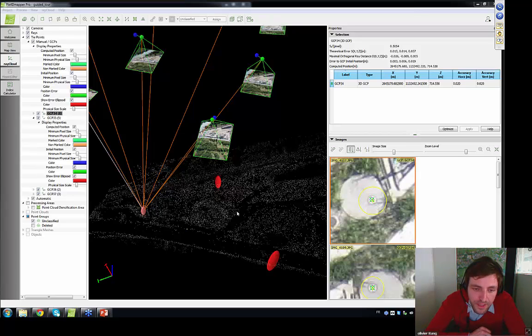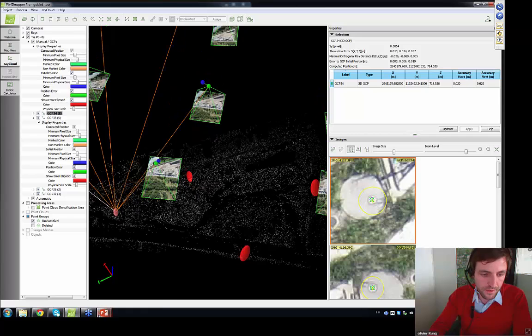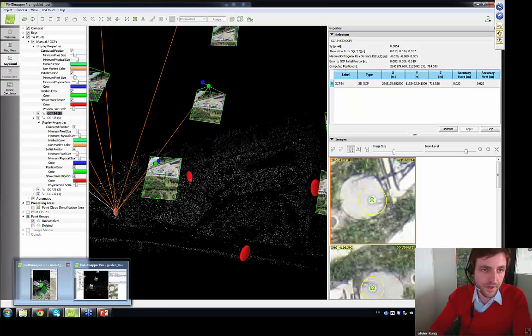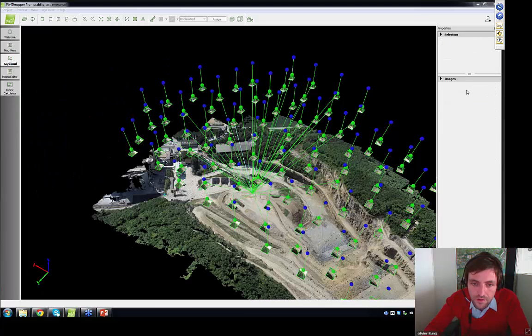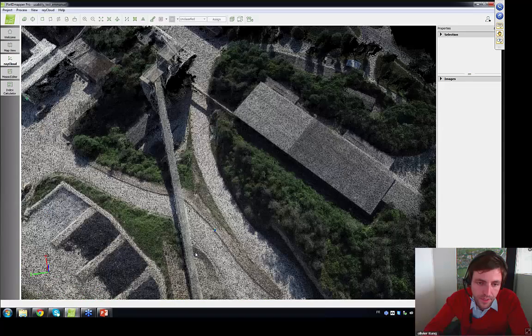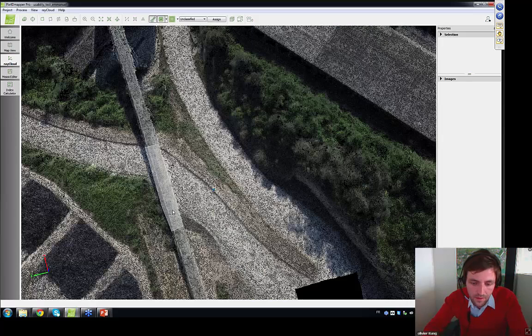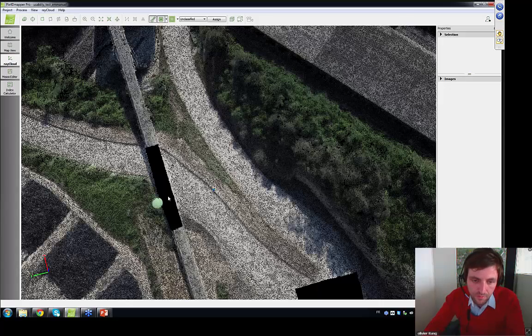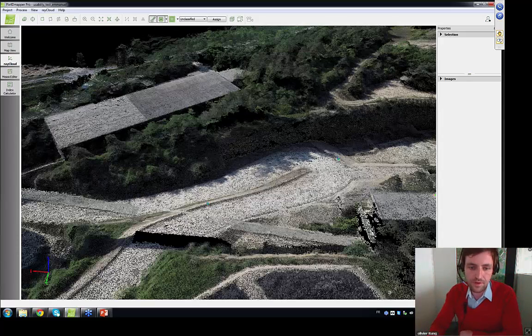Okay, another question. When removing conveyor belts above sand volumes, there are gaps. Is there a solution to close these gaps? Yes, that's a very good question. So for example, in the project, let's say I have a conveyor belt. If you remove the conveyor belt using this tool, this will basically destroy both the points on the top of the conveyor belt and on the bottom, on the road below, which could be the volume you need to measure. This is because this tool will select all the points which are below the thing you mark.